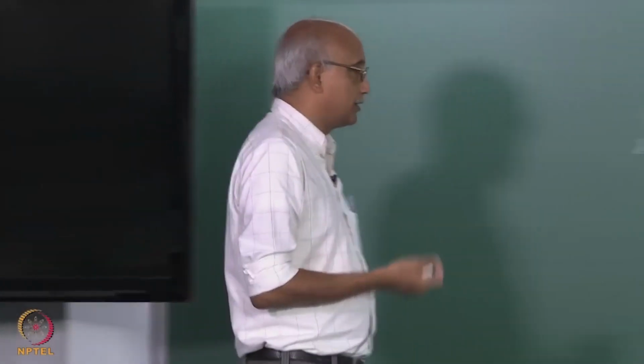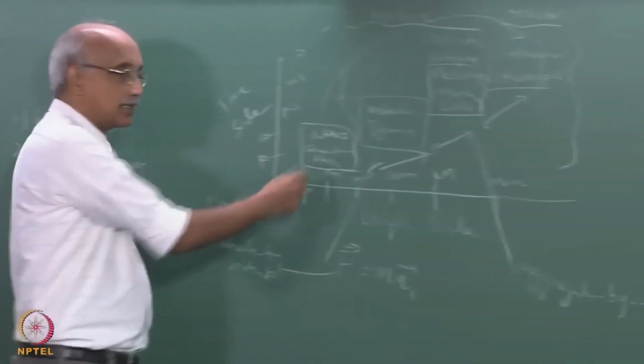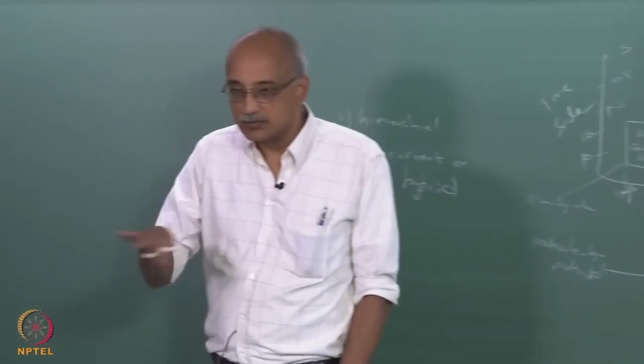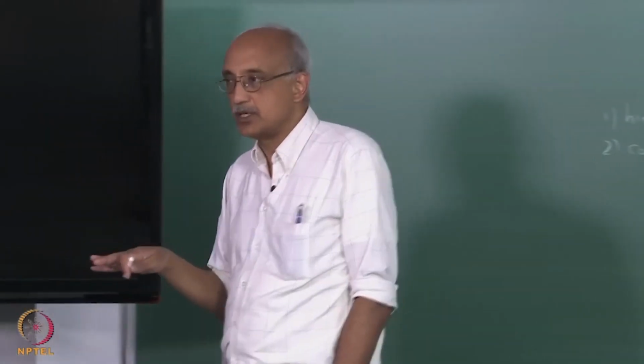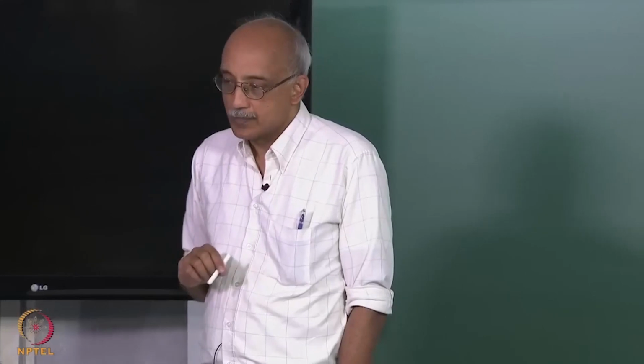The roughness of the film that you are growing on the surface is very much dependent on what is happening at this level, because when we talk about the surface roughness or surface asperities, we are typically talking about scales that are of the order of sub nanometers, particularly on highly polished semiconductor devices and so on. And the presence of even a few nano sized particles on a substrate can have a significant influence on the measurable roughness of the surface.